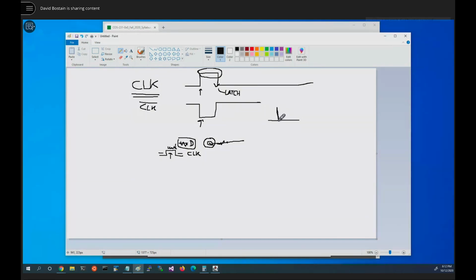Basically, there is a tiny bit of time between the up and the down, but it's in the very low nanosecond range. We're still going to latch it in effectively on the dropping clock of the spike. But the dropping clock is so close to the rising clock, and this is a rising signal, we would still call this a rising edge clock. So it's asserted only during that one little tiny period of time there.